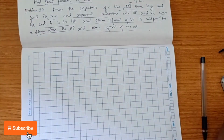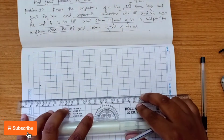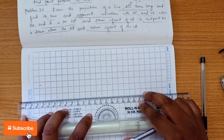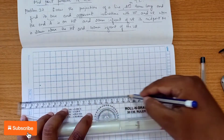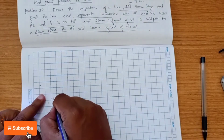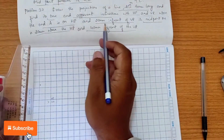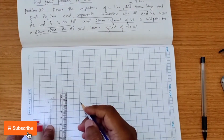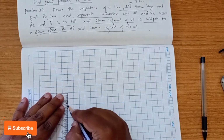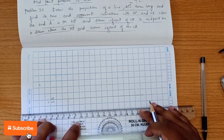So now first we are going to draw the XY line, then we draw the end points. X, VP, HP. End A is on HP and 20 mm in front of VP. So here we are going to draw a locus line.